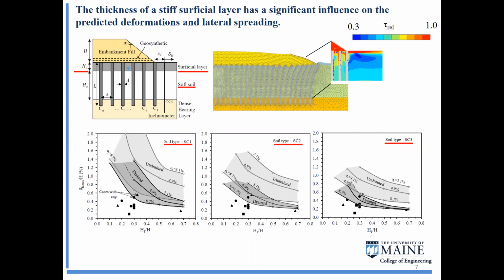Now, the magnitude and depth of stresses imposed on the soft foundation soils is limited by arching in the fill, as well as down drag associated with soil column interface friction along the elements, okay? And because stresses in the foundation materials are reduced and concentrated near the surface due to these hang-up effects, the drainage distance associated with excess pore water pressure dissipation is also much shorter, okay?